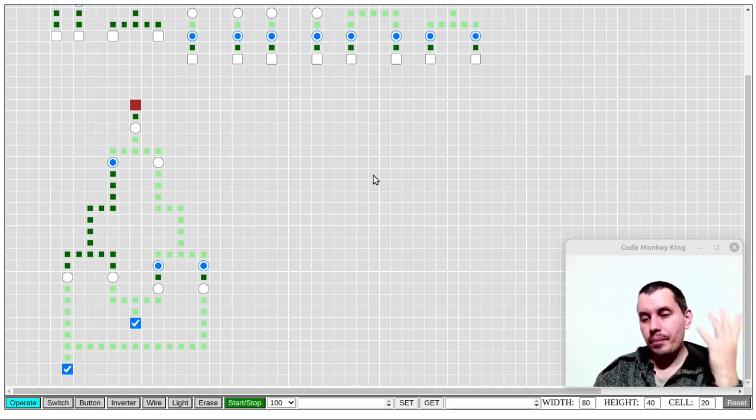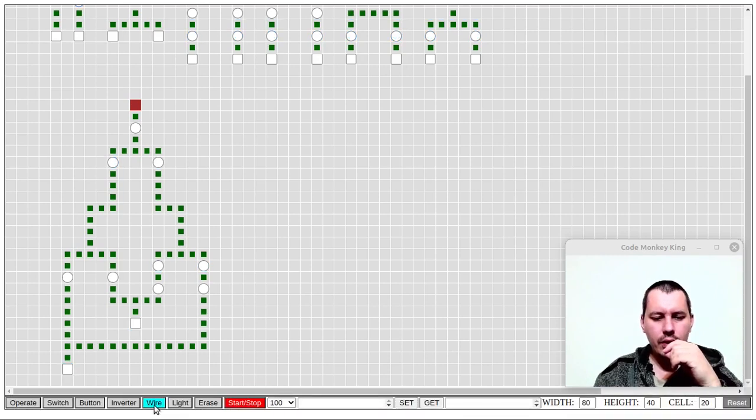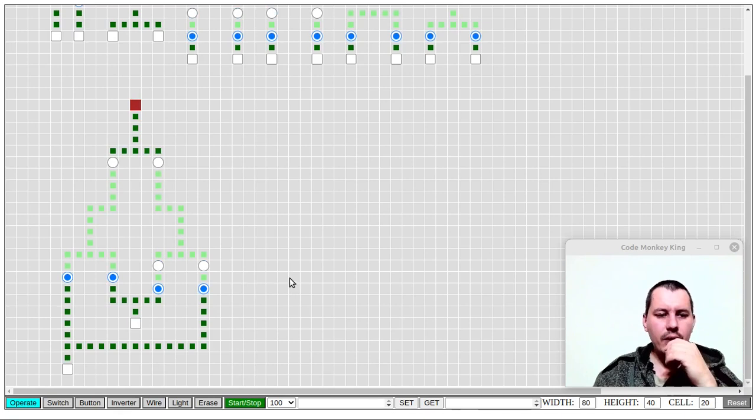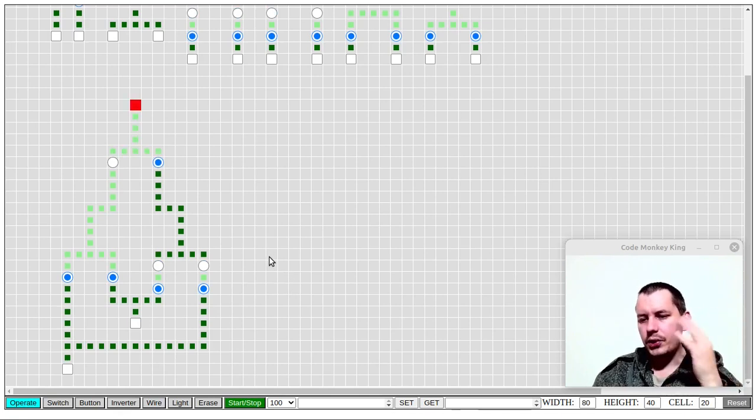And now to invert this, again, we can either put another inverter or we can just get rid of this one. So now let's stop the simulation, take the wire, put it in here, operate, and start the simulation. Now it would be XOR, but with an inverted signal. So 0 XOR 0 is 0, but we invert, so we get 1.